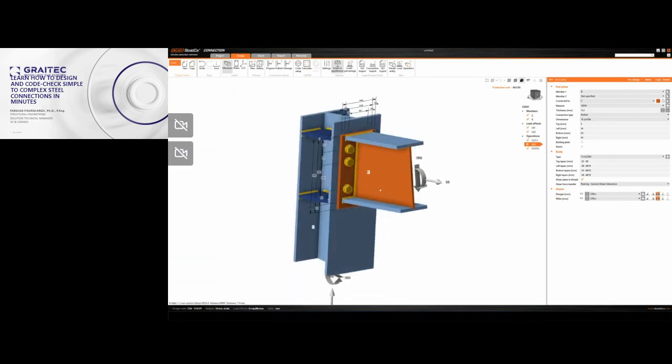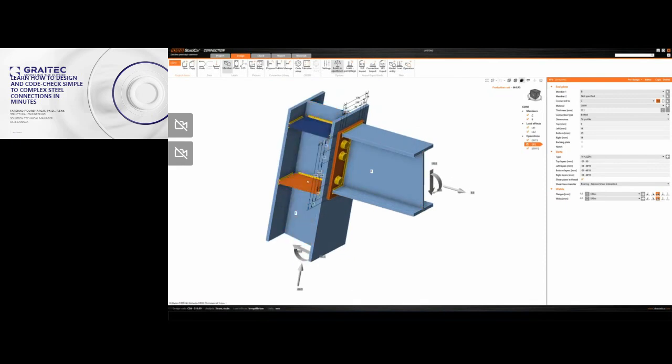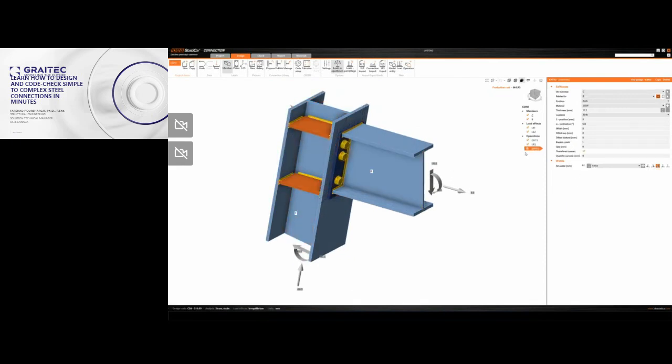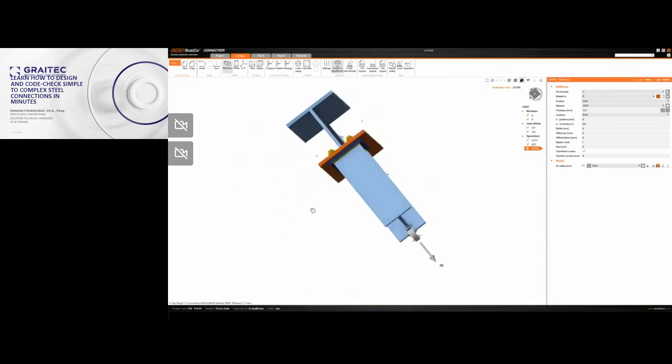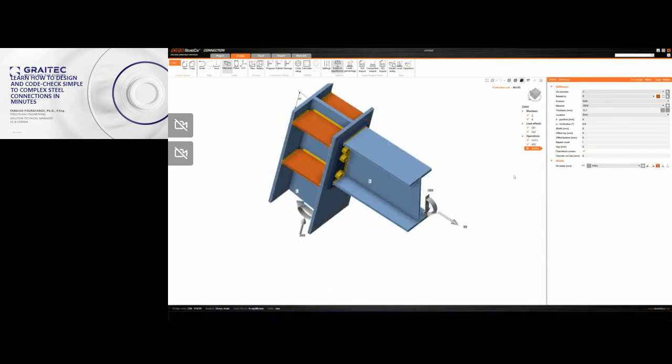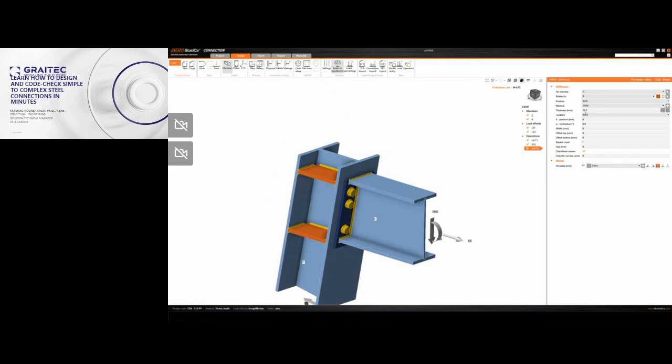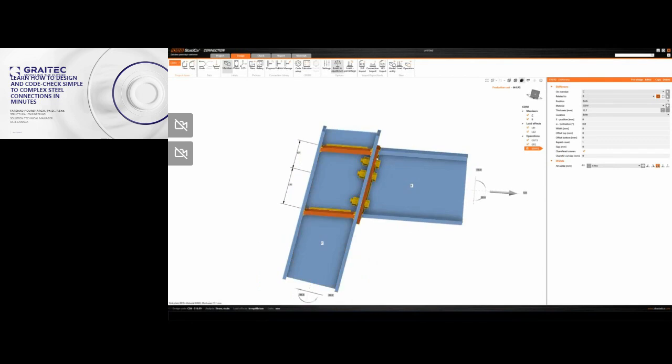And finally, we also have stiffeners here, which is again another operation. I can click on them. I can remove them just to see, there you go, it's not there, and I can add them. And similarly, their properties are here. They're going to be on member C, the column, related to member B. So it's going to automatically follow your flanges, and then you can decide where you want to put those stiffeners, the thickness, the material. You can actually offset them up and down.